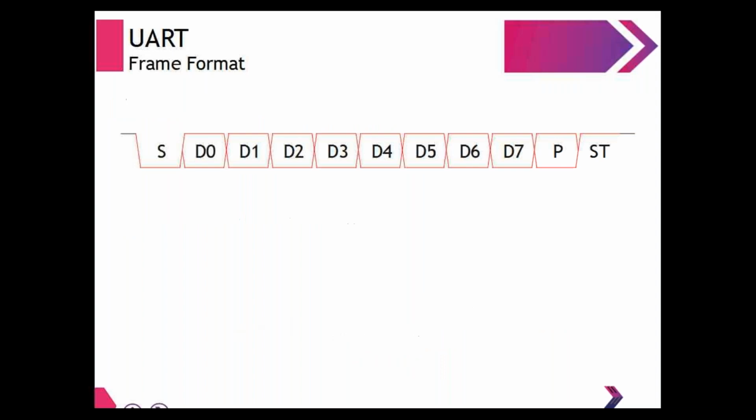Now you see this. Munir, your concern was this? Yes, whatever you are saying is correct. You see here, I'm writing everything correctly. Whenever you want to do communication, initially the signal has to change from high to low. That is nothing but the start bit. Then you have data bits D0 to D7, which could be 1 or 0. Then you have the parity bit, which is 1 or 0. And at the end, we have two stop bits, which are nothing but 1. Any doubt still now?